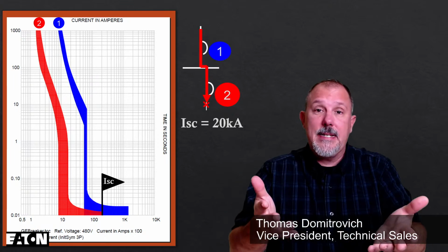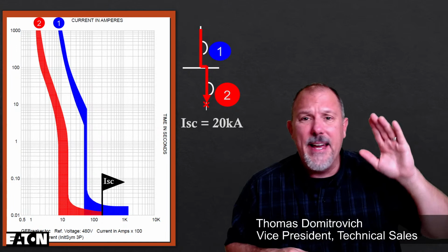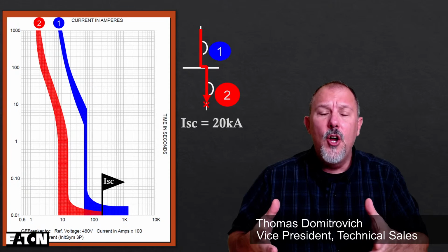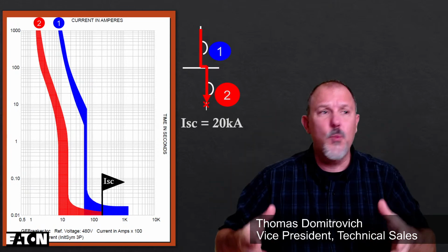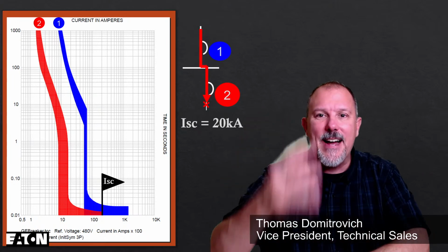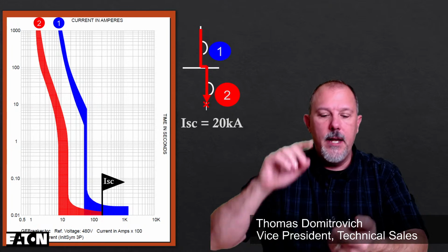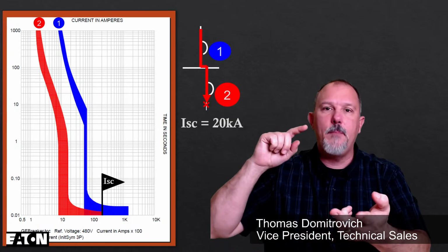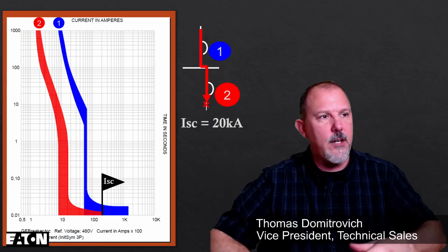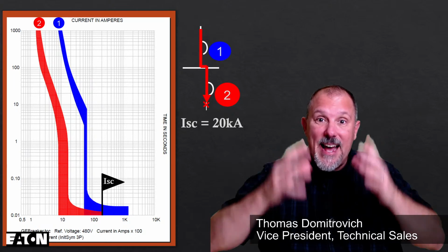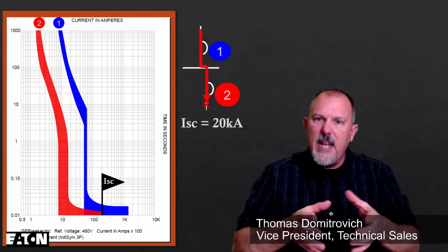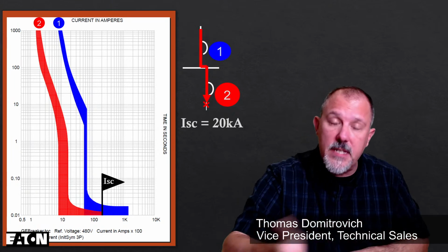If, for example, I have an area where I say, you know what, I don't care if I lose this power. Like a fire pump. Think about a fire pump. We don't care what happens to the conductors. We don't care what happens to the equipment. You want that pump to run. Your design decision is not based upon worker safety. It's not based upon protecting the integrity of the conductors so that they don't overheat and start a fire. You're worried about that fire pump running when you need it, period. So you make these design decisions, and the code permits that.